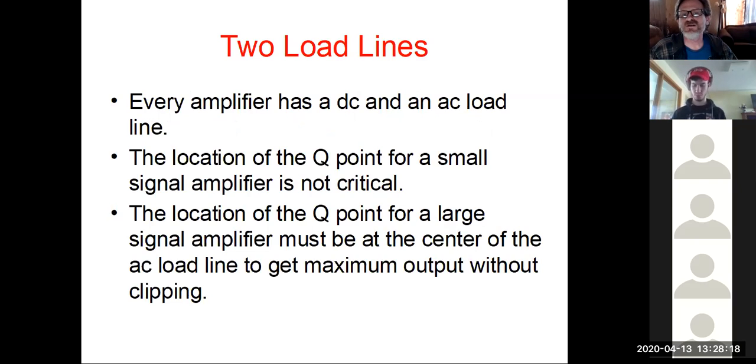Now, I know you guys are going to love this. We all love Q points so much, right? So now we're going to look at 2 Q points. We're not only going to look at the Q point for the DC response, we're going to be looking at the Q point for the DC as well as the AC. This becomes very important because, if you remember from before with the DC, the Q point was the ideal operating point for this particular transistor. Well, that applies very much to this as well, but now it gets a little more interesting.